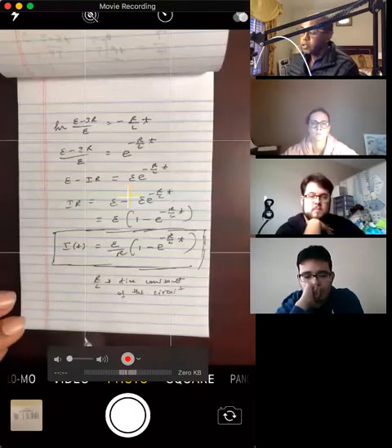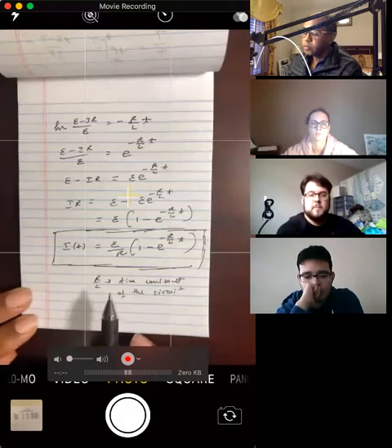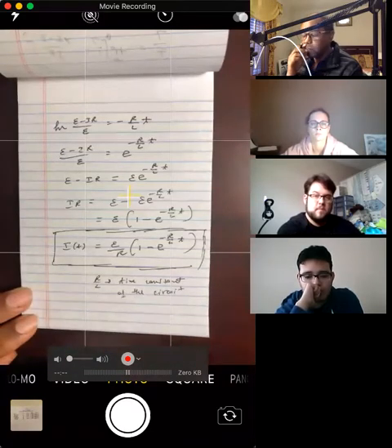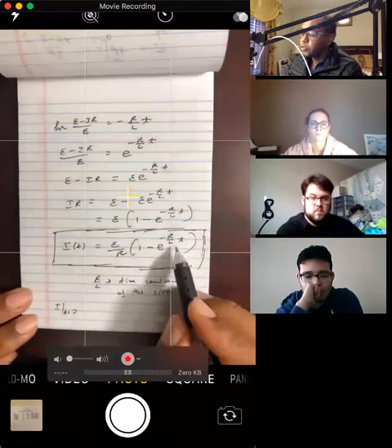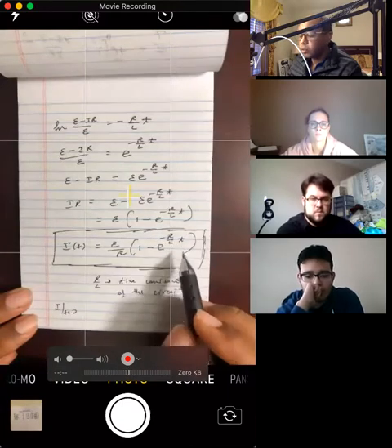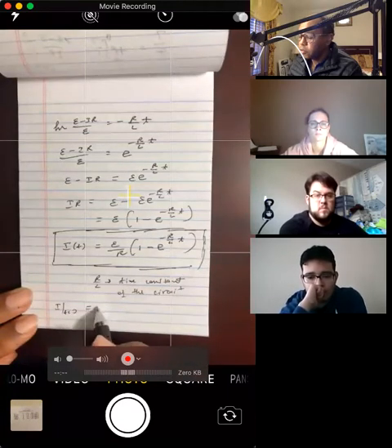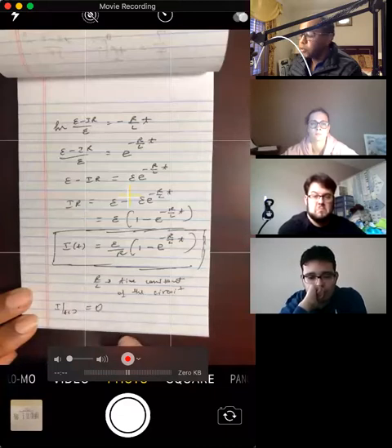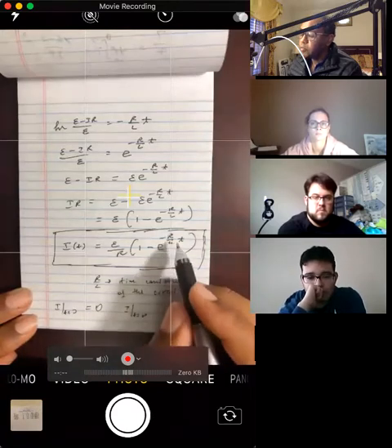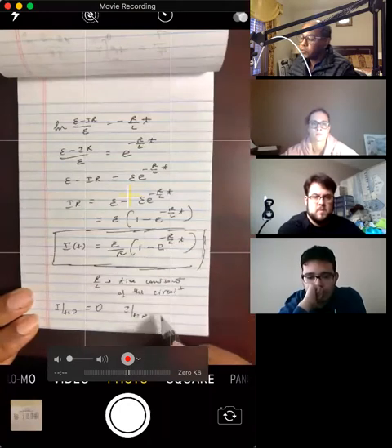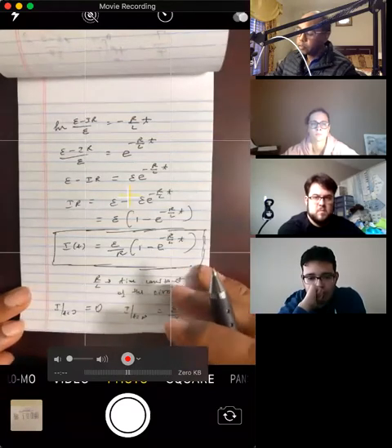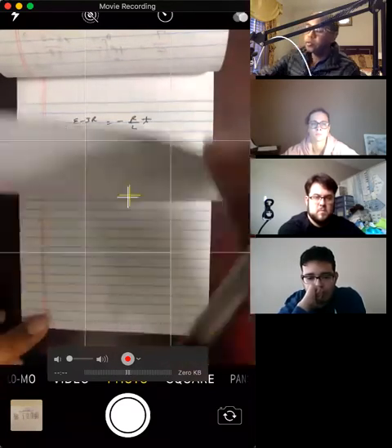All right. So let's look at the properties for 0 and infinity so that we can plot the graph approximately. So what's I at t equals 0? You see, put 0, this becomes 1. 1 minus 1, 0. So I at t equals 0 is 0. Actually, we started by assuming it's 0. And then at infinity, I at t equals infinity. You see this negative, so at infinity it is going to be 0. We just have this one over here. So this one is E over R. So now with these extreme values, we can plot the graph of the current.